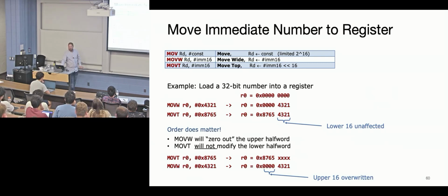Any other questions before we go on to other confusing slides? Okay. So in the homework, should we follow ARM instruction or ARM V7 instruction? We're going to use the ARM v7m architecture, and you should always use Thumb 2 instructions.